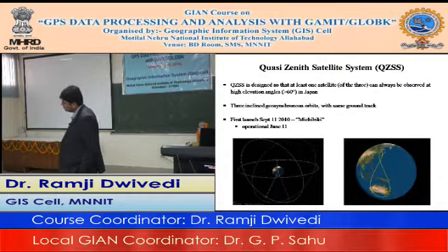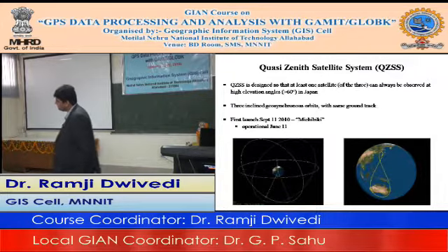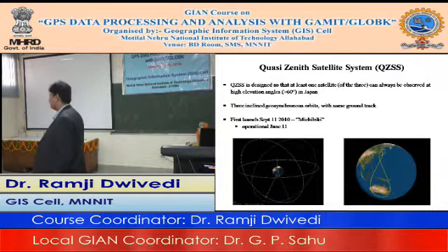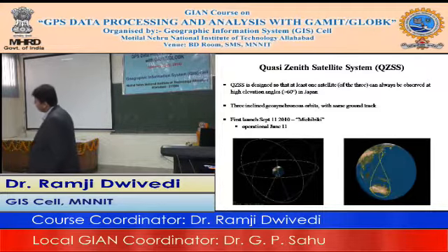The first one was probably rapid static. I think that was the first name used. But then stop and go, as I remember, is a Trimble trademark. Their receivers had a button on them which was stop and go. You'd set it someplace and it would tell you when you could go again. And then the next big evolution was the real-time kinematic. What that did was it took the data transmitted by radio link and processed it in the rover receiver. So in real-time kinematic, you knew exactly how good this position was, and the receiver could then tell you definitively you can move.